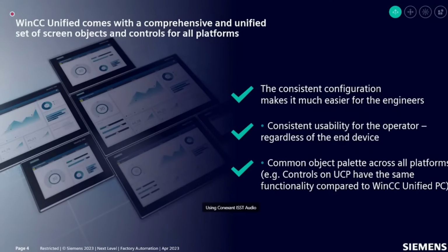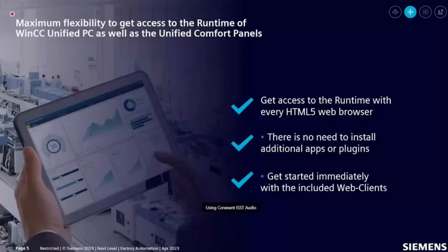And from the flexibility point of view, as I said, for the user, unlike our other SCADA systems, we don't need any extra installation of a client system to access the SCADA screen. The user just requires an HTML5 browser on the device. Through that, they can access the SCADA web page. And there is no requirement to install any additional software to access this client screen. So that is also another benefit. And by default, when you use this web-based SCADA system, you will get the web client also included for monitoring purposes.